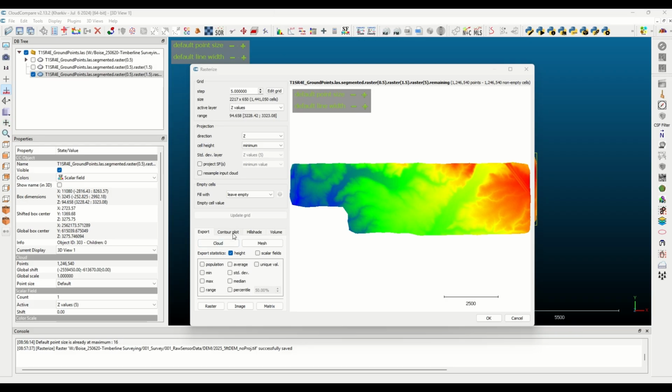And now the last step is to contour. So we're going to set our 0, and then we'll set our step to 0.25 and our minimum vertex count, just to ensure that we're not picking up crazy small features like sagebrush and outcrops.